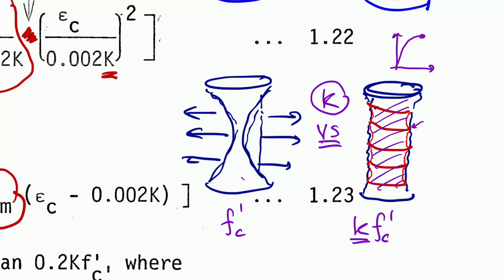I mean, if you put a strain gauge on a steel hoop and check the strain of the steel versus the strain of concrete, concrete undergoes the strain in this direction, steel is in the orthogonal direction. Steel isn't supposed to act or carry anything. So in the initial part of the curve of the concrete, participation from steel is not so high.